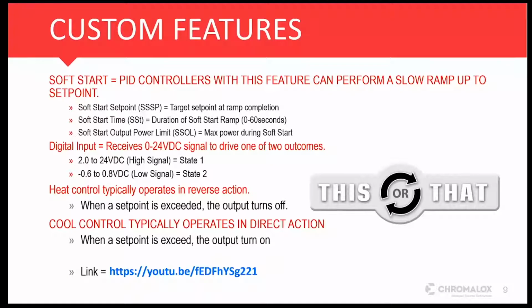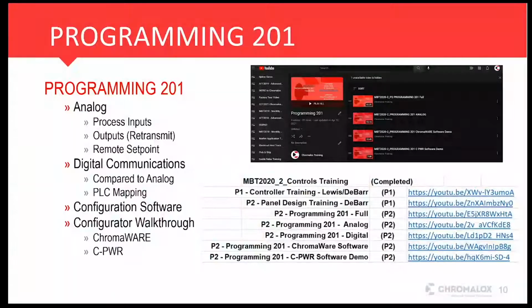Think of reverse acting versus direct acting. Well, what do those terms mean? Well, actually, reverse acting, you've got to think of it as your heating cycle. You're heating up, as opposed to direct acting, which would be more of a cooling cycle. Vince will touch on that and explain that a little further in a minute.